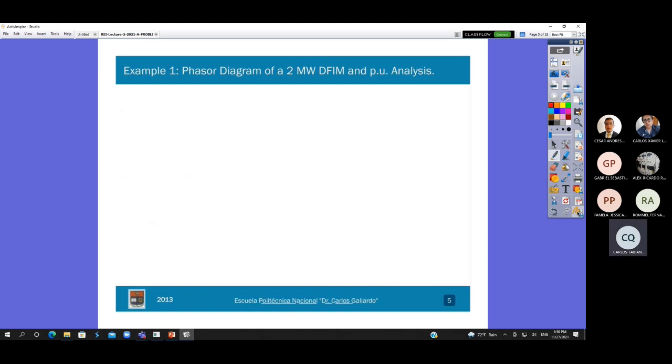From the required DC bus voltage perspective, taking into account that these phasors are root mean square values, ideally, the required minimum DC bus voltage to handle this rotor voltage amplitude would be as follows. The root mean square value of the voltage is, by definition, equal to the peak value over the square root of 2.